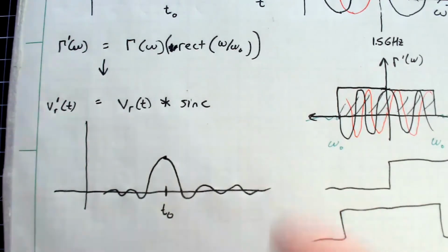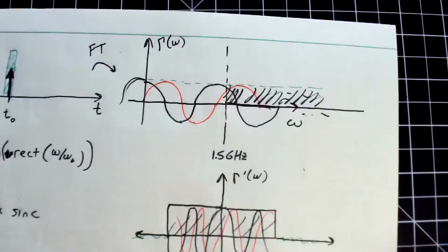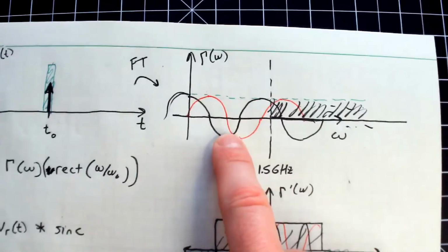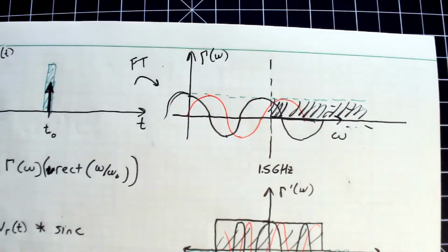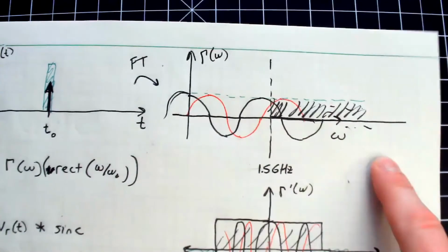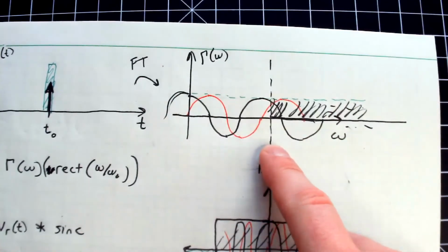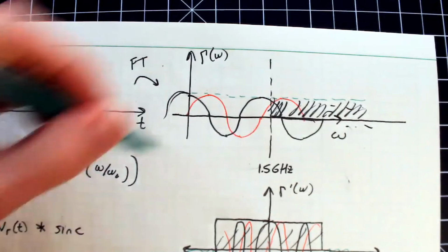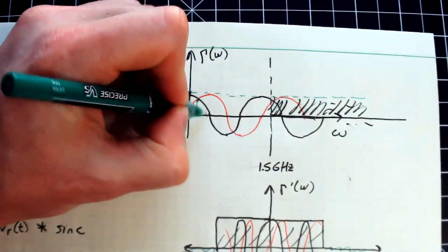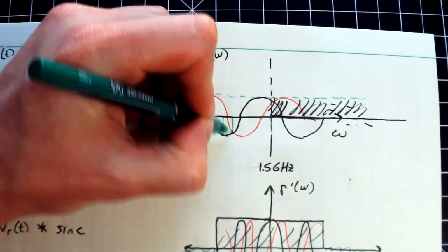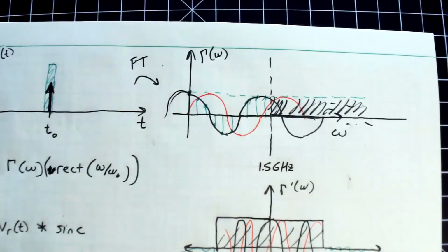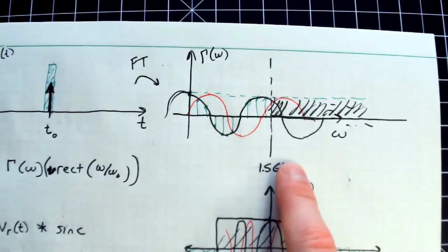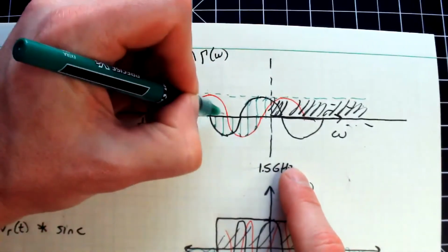However, there is one extra layer of squishiness on top of this that we have to account for. And that is, here's my true Fourier transform, right? When I do this with the nano VNA, I'm not doing a continuous, infinite number of samples here. What you're actually doing is sampling it at discrete values. So I've got a point here and a point here and a point here, like this. So there's 101 samples of this thing, both real and imaginary values, like that.